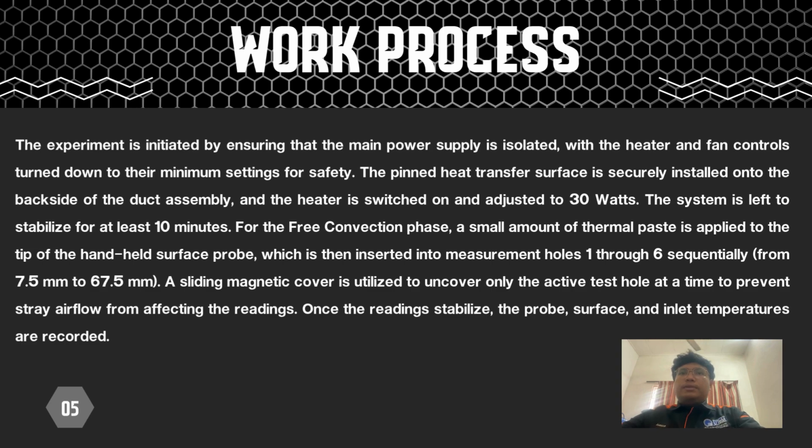During the free convection process, thermal paste was applied to the probe before taking temperature measurements from hole 1 until hole 6. A sliding magnetic cover was used to prevent stray airflow from affecting the readings. After the temperature became stable, all readings were recorded carefully.